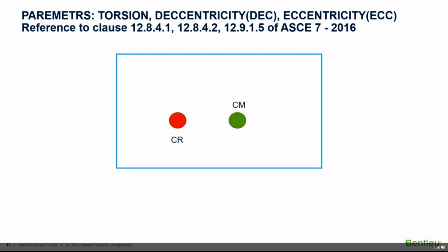If you remember, we had talked about an additional load case in each direction without torsion being considered, which is to be used in such 30% combination cases. Thus, this would result in the doubling of the pure earthquake combinations from 8 to 16 to give the resultant earthquake forces in the two orthogonal directions.